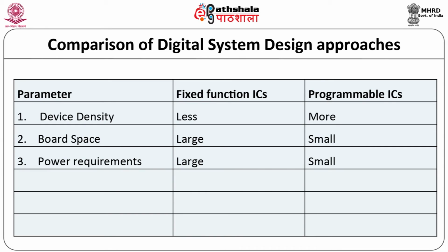The power requirement of fixed function ICs is larger because it utilizes discrete components, whereas the programmable approach utilizes a single chip solution. That is why the power requirement is also low. Normally for fixed function ICs, the development time is less, whereas in case of programmable ICs, the development time is more.